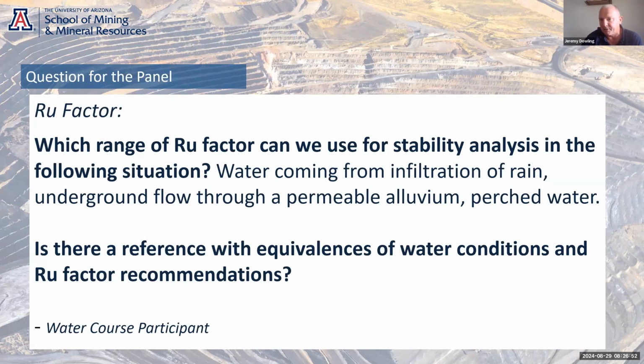and then used it as a kind of a screening tool to try and see which sectors of the slope appear most vulnerable stability-wise to shallow and transient water, and then use that as a basis to try and focus future monitoring. So put piezometers and monitoring instruments in the areas that show the most geotechnical vulnerability to shallow water.